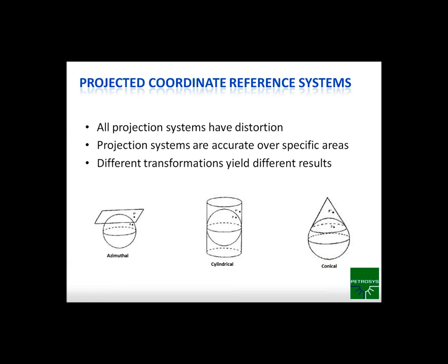And so these things aren't hard and set. Once you've decided you have your projected coordinates, they can be transformed to another one as long as you know enough information. So it's really important when people are getting data that they have some idea of what the geographic CRS and projected CRS is. And I'm going to, once I pop open Petrosys, show you a couple examples of what happens whenever you don't use the correct CRS. You basically end up getting maps that are just completely incorrect.